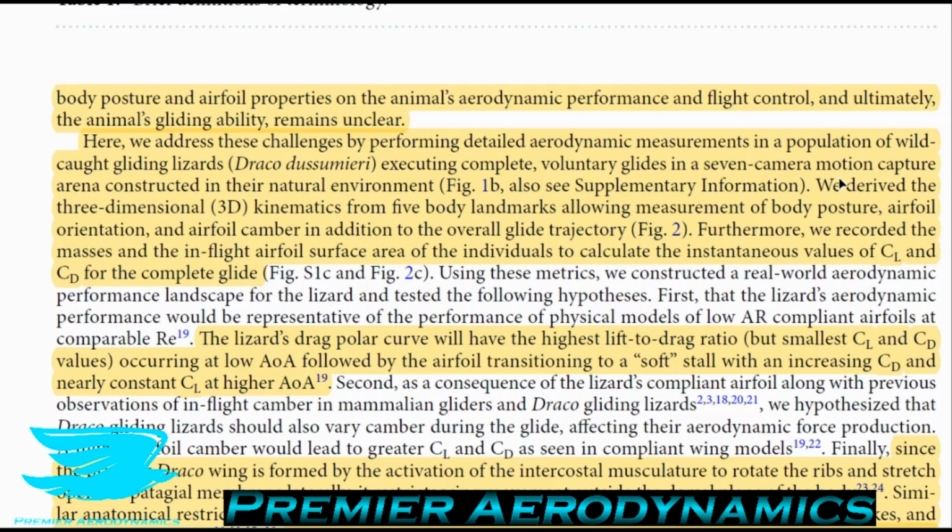And if you look at curves for regular airfoils, the lift coefficient will be linear with angle of attack to begin with, whereas the drag coefficient will be more like parabolic. So that means that as you get to higher angles of attack, the drag just skyrockets. At the low angles of attack range, the drag stays fairly constant. So it might be 0.02, for example, for a 0021 at 1 degree, and the lift coefficient will be 0.1. So you get a very good lift-to-drag ratio there, whereas when you go higher, you get worse results.